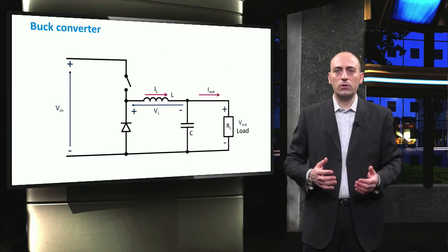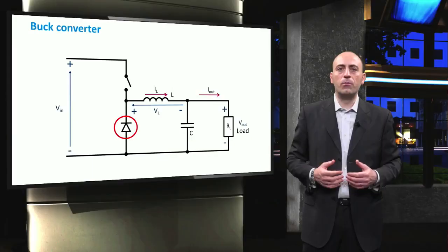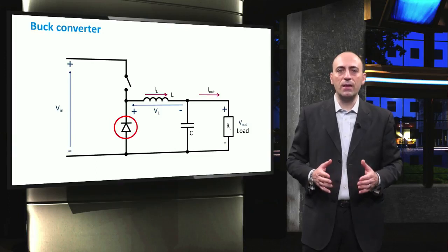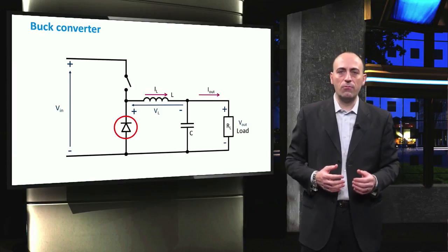This is the topology of a more complex step-down converter. Once again, we have the switch here and the load, which is purely resistive. The filter elements implemented are an inductor, L, and a capacitor, C. In this configuration, you can also see the flyback diode. Notice that in this case, the polarity of the PV module is the same as the load. Then both PV module and the load have the positive sides connected with the same branch.